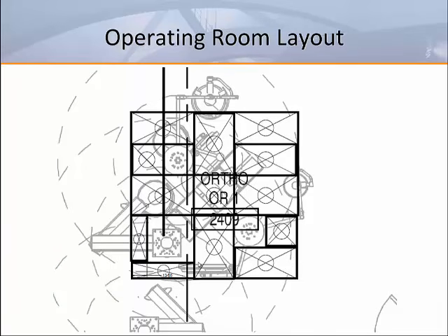A benefit of such a system is that it allows for diffusers to be installed much closer to one another than with conventional monolithic ceiling construction. While the unidirectional diffusers are designed to entrain only minimum amounts of air, larger spacing between diffusers allows for more air to be entrained into the aseptic field. Minimizing the spacing between diffusers aids in the prevention of surgical site infections.